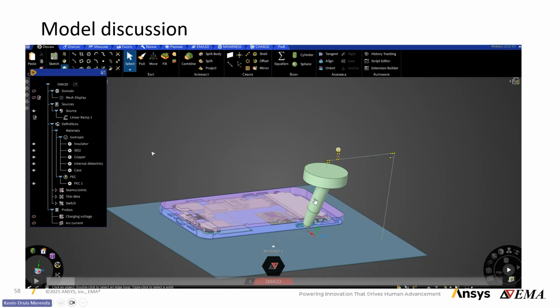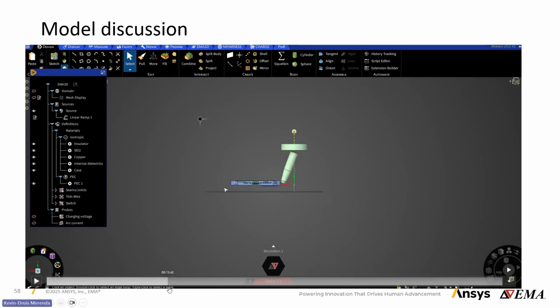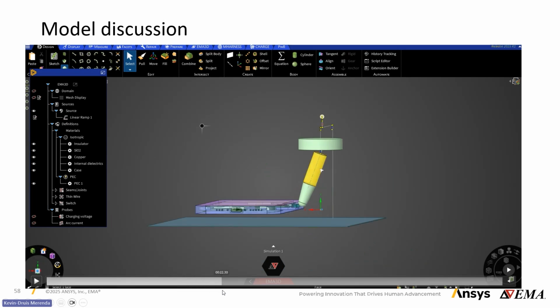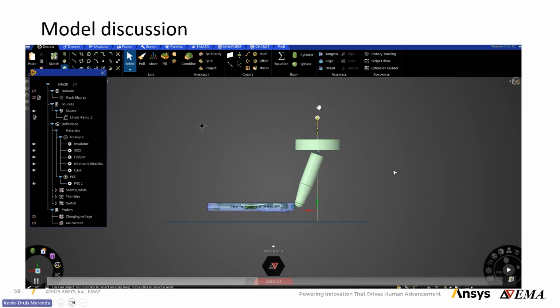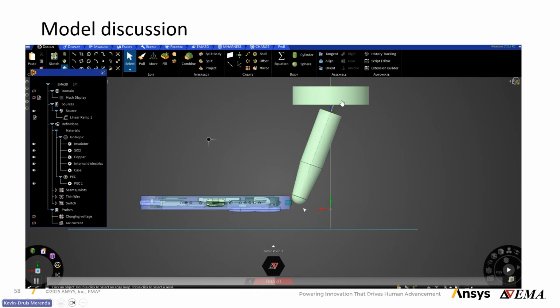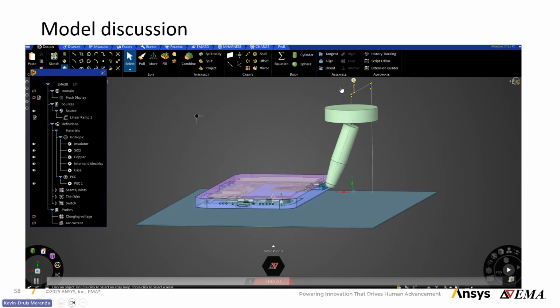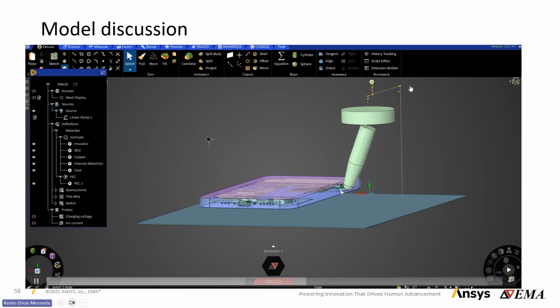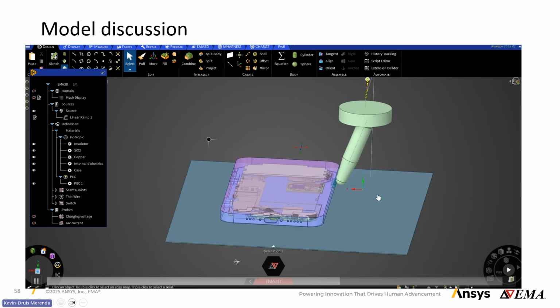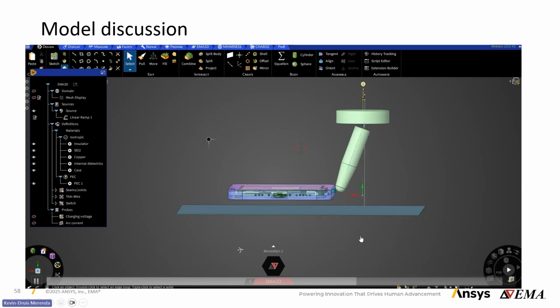And then you can change the ESD gun tip very easily. So move it around. This will help you reproduce your test setup environment. So if you move around here, we can look at the angle that we set up. We have all the components, the voltage source at the top. We have the switches, the 330 ohms present as well. And then we have our ground return strap that is also modeled and connected here to our ground plane.